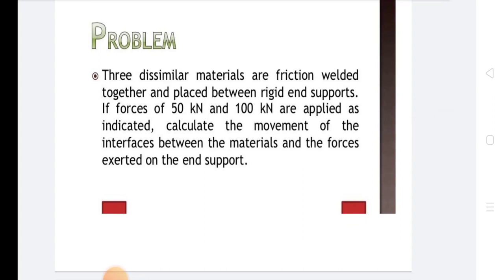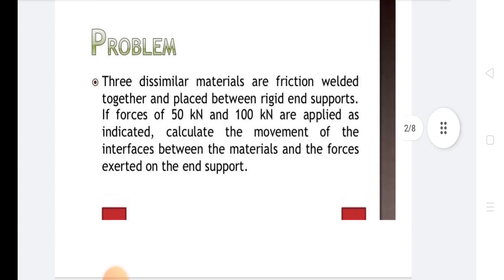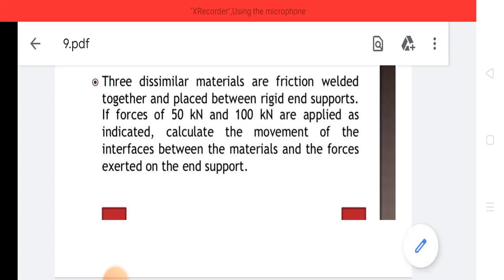Out of the two, the one preferred for FEM is the polynomial function for its ease of mathematical calculation. The displacement model selected is governed by three conditions: type and order of functions. The type of function selected may be polynomial or trigonometric. As for the order of the function, if it is of nth order, then the solution for the problem is exact. An approximate solution could be obtained by truncating the polynomial to finite order.